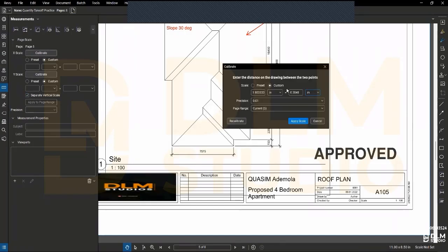Once this is in meters, you deduct that manually. You get the square area. Once you have the square area of windows and square area of doors, you now deduct manually, like pressing the total square area of your wall minus square area of your window minus square area of your door.